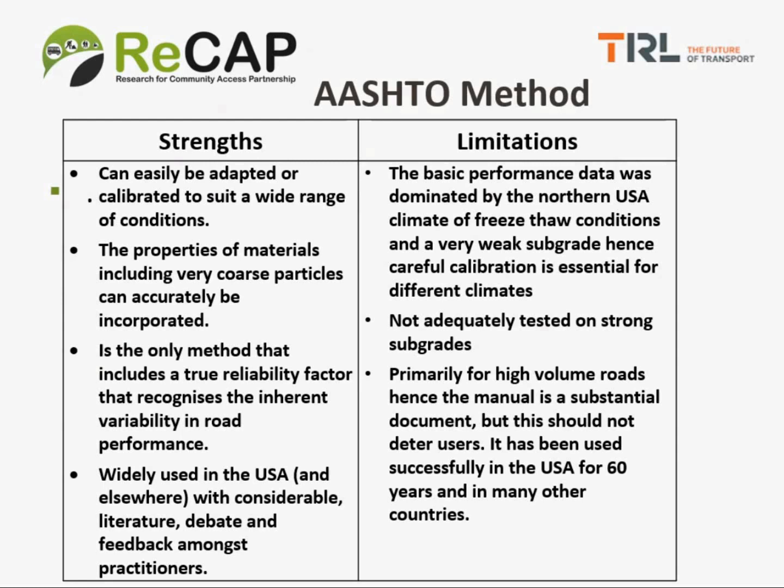It is also the only method that includes a true, what I've called a reliability factor, that recognises the inherent variability in road performance. That is taken into account explicitly in the design equation and allows you to design essentially to cope with variability. You can choose your level of risk, in other words. I did say earlier on that each method deals with risk in a different way. This method allows you to design for 95% reliability, very, very little risk of failure.